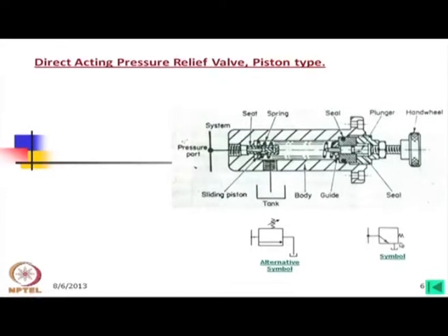There is only a rare case where a fixed type spring is used, a fixed compressed spring, and that is a set relief valve. Usually inside some systems a set relief valve is used. It is also possible that it is prefixed and it is a fixed one, that means the set pressure is always the same.